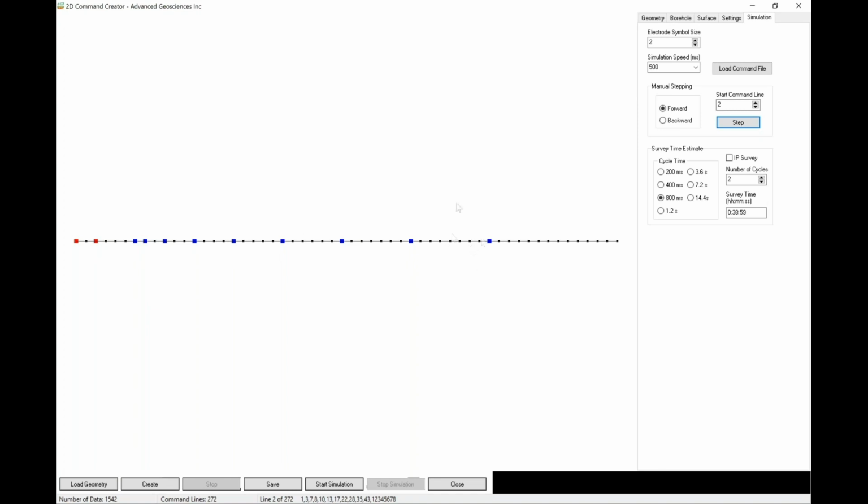Voltage falls off with distance from the transmitter. So a wider dipole spacing will give you larger potential. So that's going to increase our signal to noise. So it's collecting it in a higher signal way. And you can see that it steps like that with telescoping dipoles.